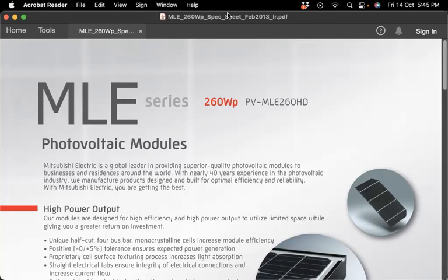If you remember, in the second part of chapter 2, we studied together the IV characteristic curves for a solar cell. And we understood some major parameters like the open circuit voltage, the short circuit current, the maximum power point, the current at which the power is maximum, or what's called IMP, and the voltage at which the power is maximum, the fill factor concepts, and all these things. But these were somehow focused on the cell level. Now we are going to demonstrate this on a module level.